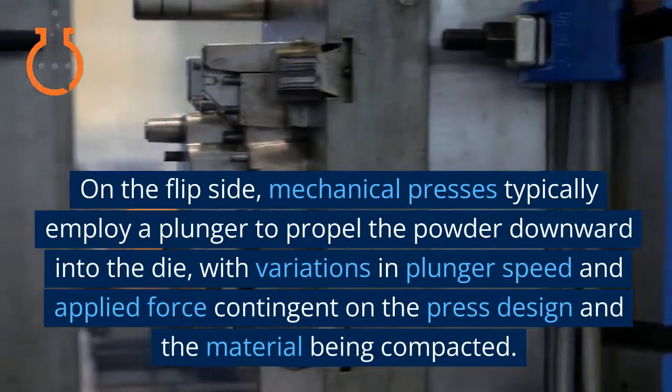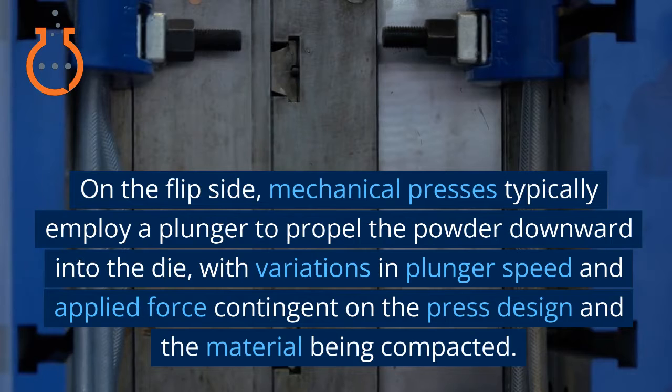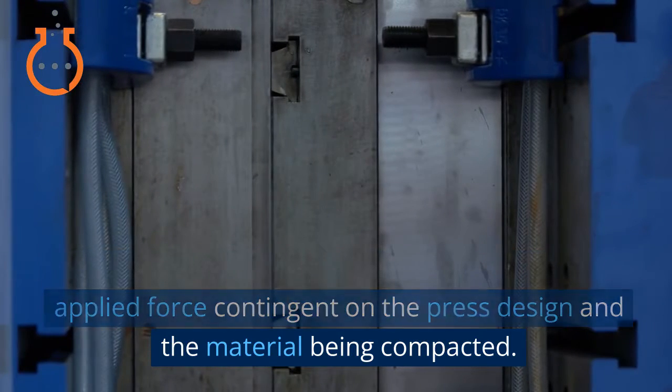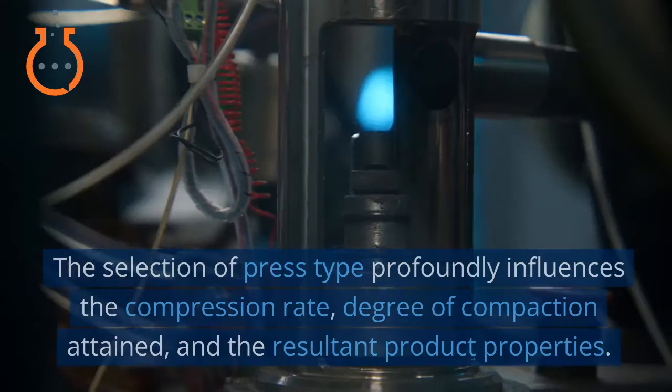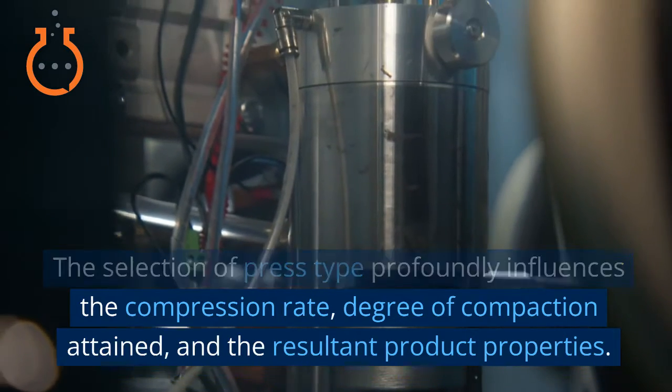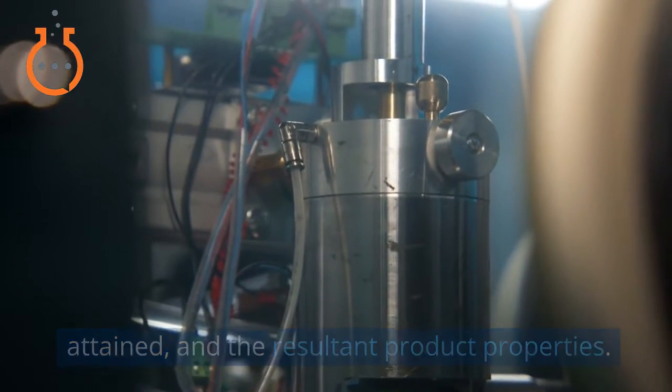On the flip side, mechanical presses typically employ a plunger to propel the powder downward into the die, with variations in plunger speed and applied force contingent on the press design and the material being compacted. The selection of press type profoundly influences the compression rate, degree of compaction attained, and the resultant product properties.